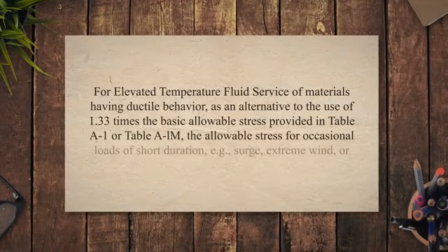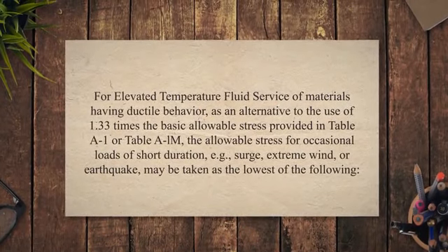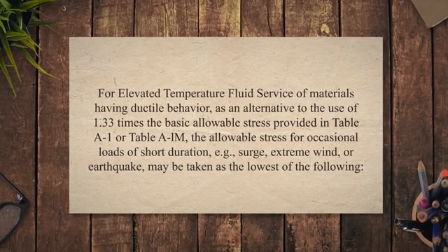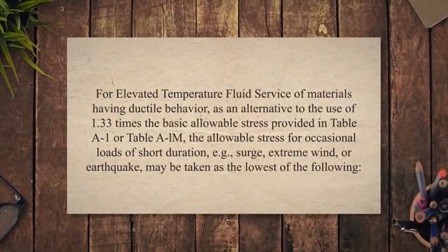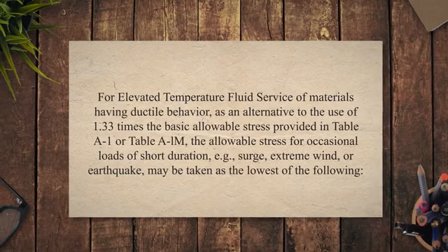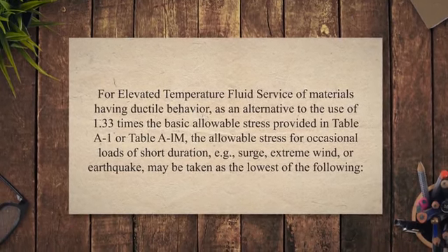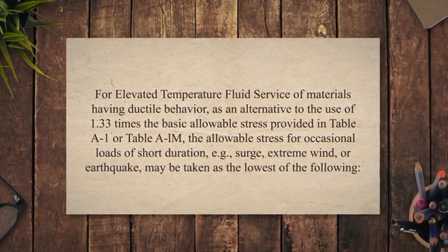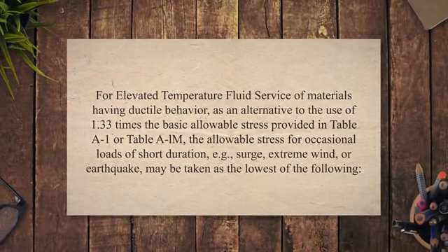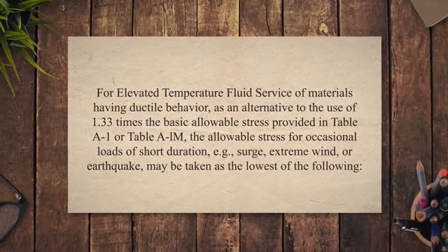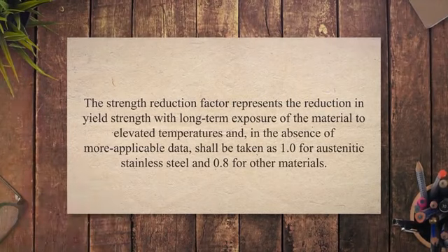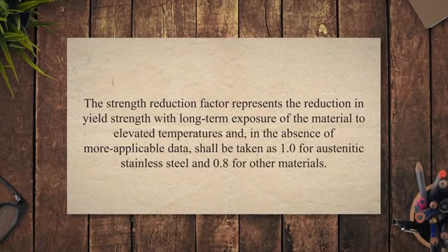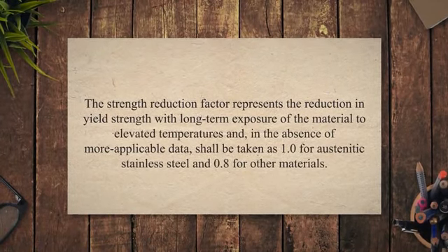For elevated temperature fluid service of materials having ductile behavior, as an alternative to the use of 1.33 times the basic allowable stress provided in Table A-1 or Table A-1M, the allowable stress for occasional loads of short duration, for example, surge, extreme wind, or earthquake, may be taken as the lowest of the following. A. The strength reduction factor times 90% of the yield strength at the metal temperature for the occasional condition being